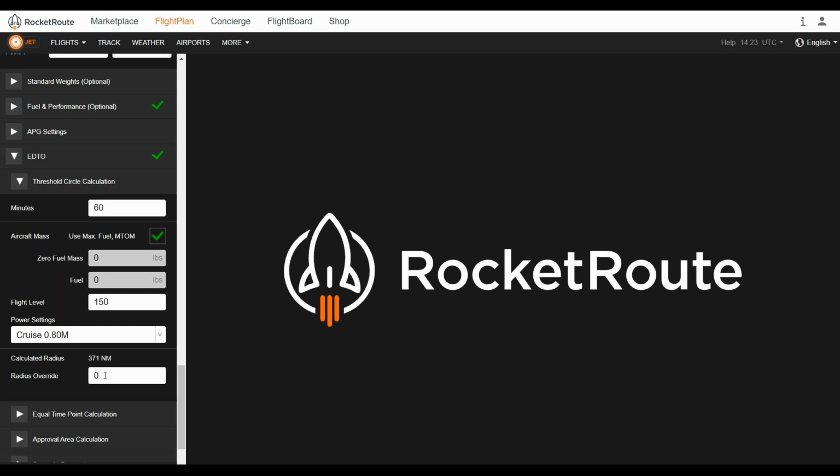If you override this radius, all other settings above will be ignored, and the value that you entered in the radius override field will be used as the radius of the threshold circle. We also have this checkbox here, use max fuel and maximum takeoff mass. If you disable it, the zero fuel mass and fuel fields are enabled, and you can define the specific mass and fuel required for you.